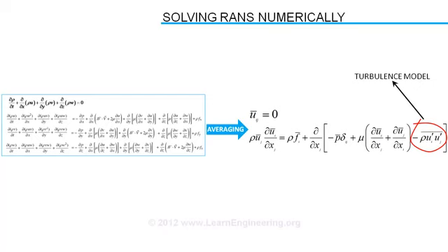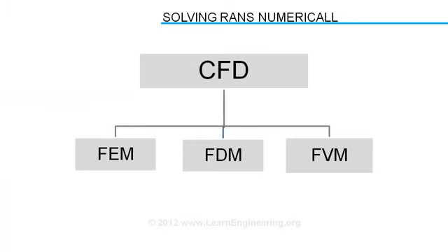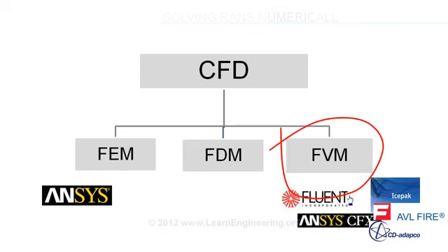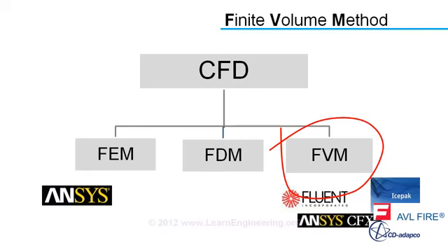Current CFD packages use the following numerical methods: FEM, FDM, and FVM. Some commercial packages using these methods are listed here. It is clear that FVM is the most common method of all. So in this lecture we will concentrate only on FVM. So, let's go across it.